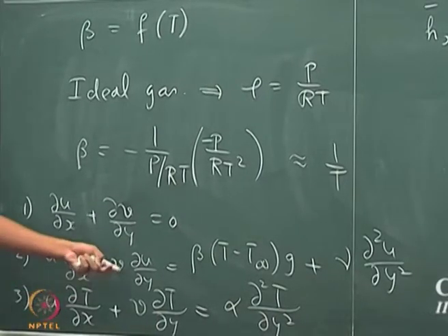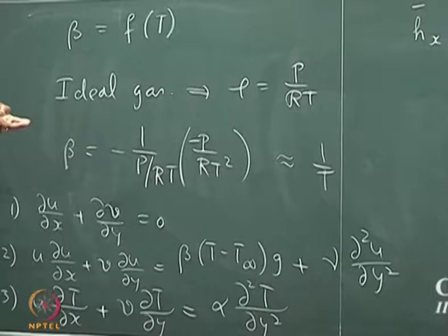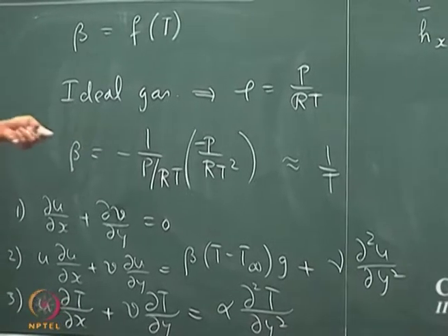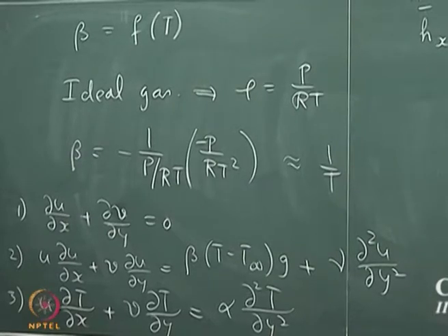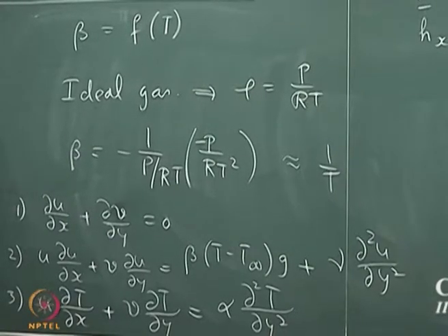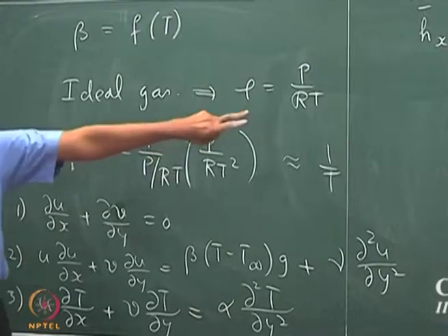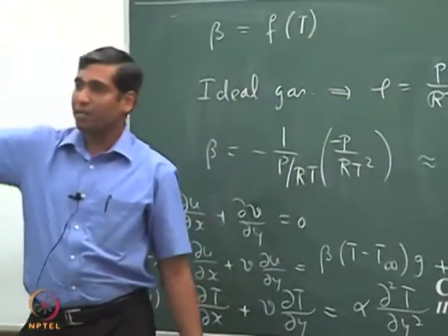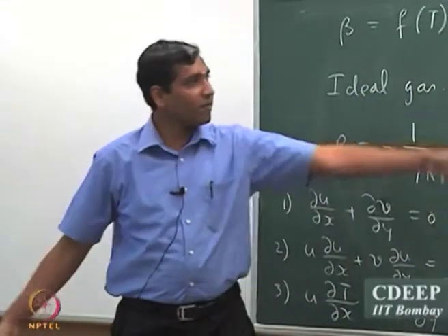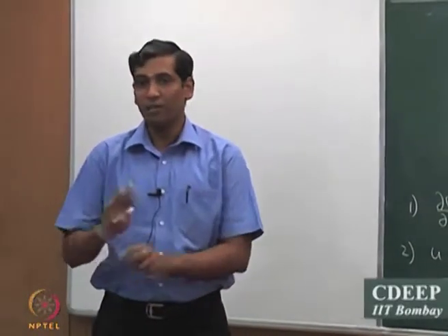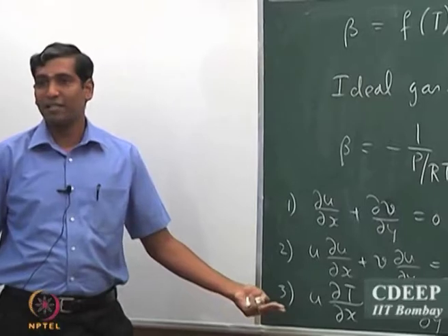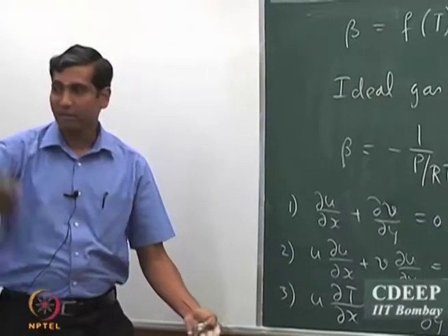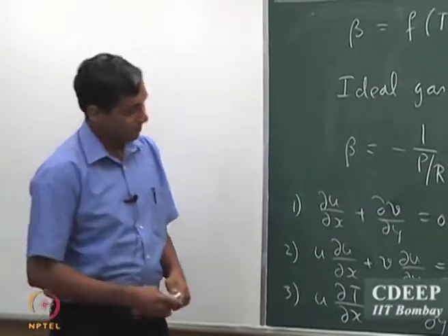So we have to solve some of these equations in order to find the heat transport coefficient. Remember that if we know the gradient at the wall, we are done, right? So heat transport coefficient, because the temperature of the plate is constant and the bulk temperature is constant. So if we know the gradient at the wall, we are done. So the objective is really to find the temperature gradient at the interface between the plate and the quiescent fluid.